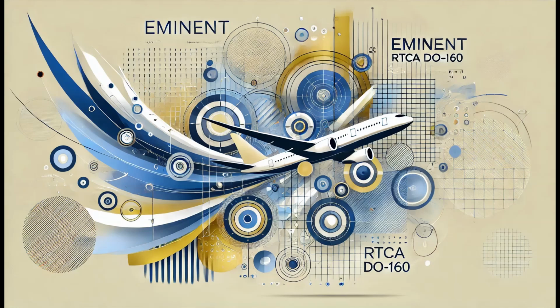Typical failures in temperature variation testing and their mitigations. Temperature variation testing often exposes specific failure points in equipment, particularly in systems that rely on stability and integrity to function effectively. Thermal expansion, leading to cracking: repeated temperature shifts cause components to expand and contract, which can lead to cracking, especially in metal and plastic materials. Mitigation: using materials with low thermal expansion coefficients and stress relief designs helps reduce cracking risks.